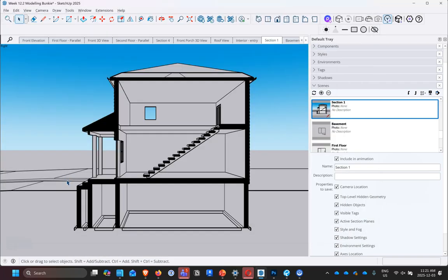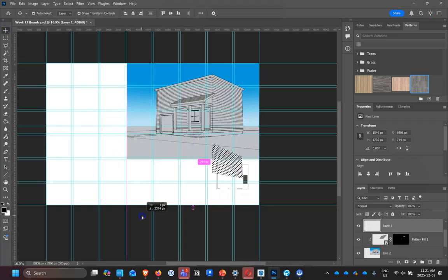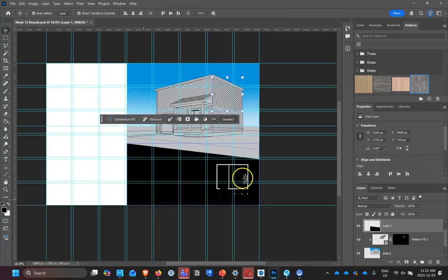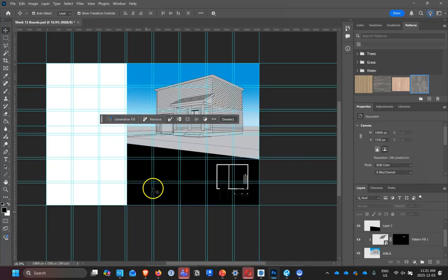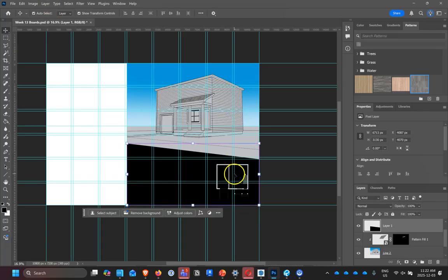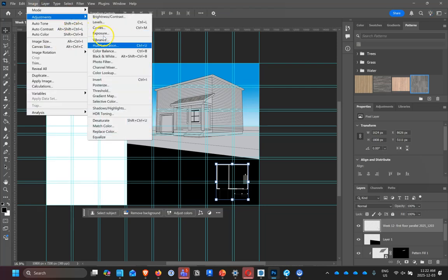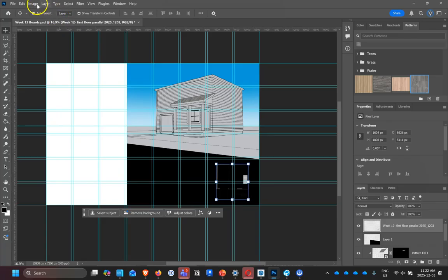And so we're bringing that view in. When we bring this into Photoshop, we've got our Photoshop here. This is something we worked on in the other class. I've taken this black box here and applied that and put our floor plan on that. When I brought in the floor plan, I actually just inverted it. If you click on the floor plan, let's deselect that, and on the floor plan here, you go up to Image, Adjustments, Invert. You can take that from black to white.